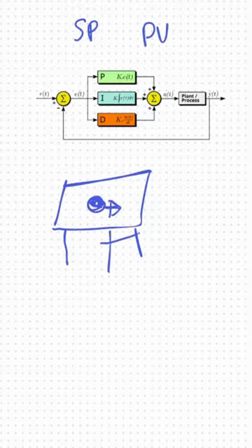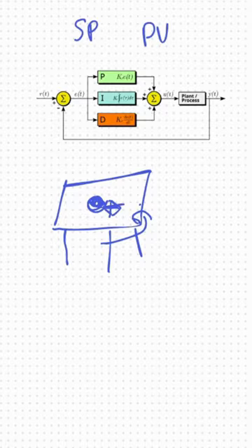Now this way works, but what happens if we tilt the board too suddenly? Due to this, the ball may overshoot and fall off the board. So this is why we need all three terms of the PID controller, the terms being P, I and D. So let us look at their importance.